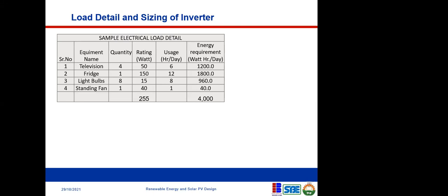So this is a sample electrical load detail. Now this is just for simplicity's sake. We just assume television, the quantity is 4, fridge 1, lighting bulb 8, standing fan 1, and these are their power ratings. So in all, we require 255 watts, which is about 0.255 kilowatts of power. So we know what our power is. Then secondly, we need to determine the number of hours that they use this load. So for television, we assume that they're going to run it for 6 hours on a daily basis.